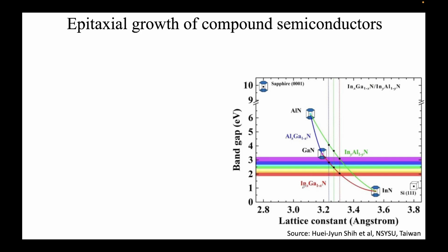So it will have the expression InxGa1-xN. On the green line, on the other hand, you have indium aluminum nitride, so aluminum nitride and indium nitride, and you can see it will look something like this. You can also see it's not a straight line; there is a bow associated with that. This bow is coming because on my axis we have the band gap. It's most clearly seen in terms of indium gallium nitride. You can see there is a significant bow to this. That's coming essentially from the bowing parameter of Vegard's law in context of the band gap.